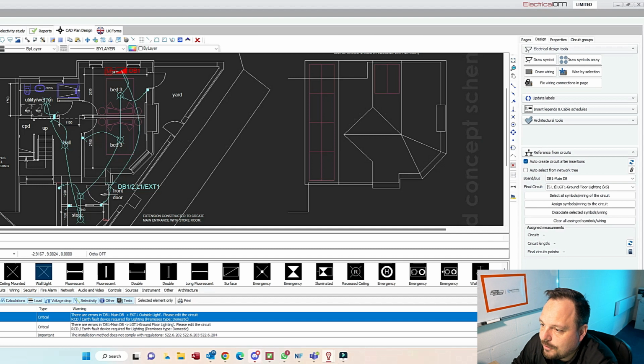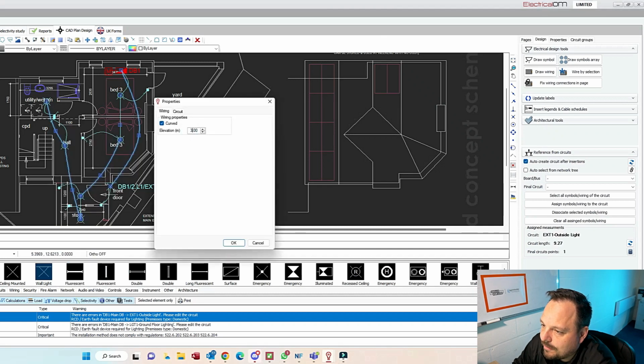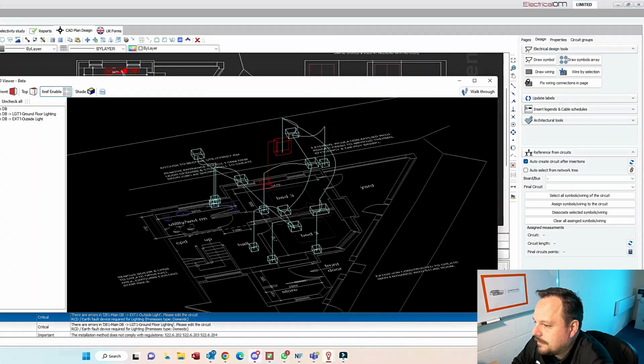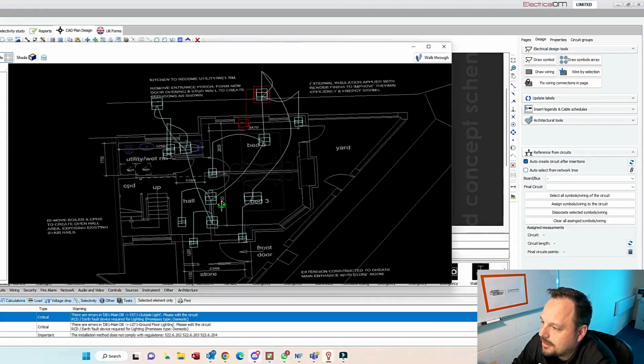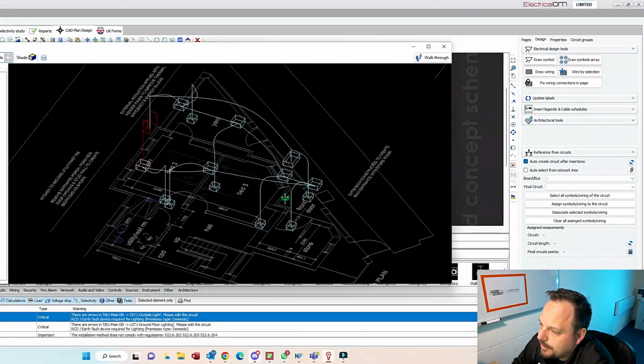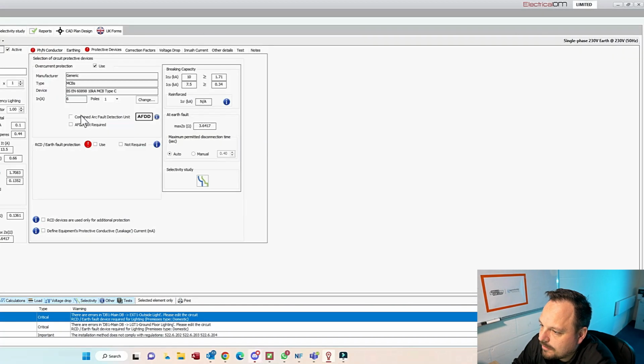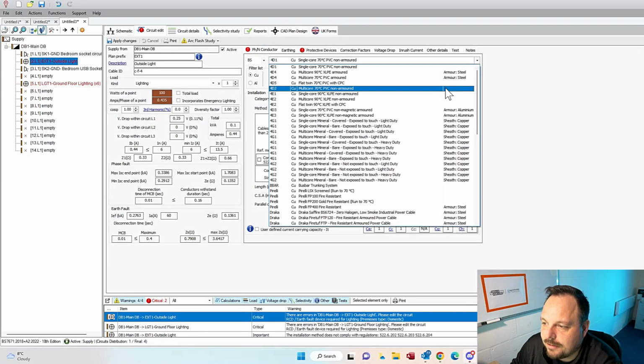Now the 3D function is really useful here again because you can check that you've got all of your heights set correctly. Anything that you've not done becomes obvious. You can see I've clicked off and seen that I've not set these to the right height again, so we make that edit, and hopefully now we will have all of the cabling in the right place. As you see, if I drag that 3D view in, we've just got the layer on for the lighting in the distribution board, and we can see all of those drops are running in the right direction.